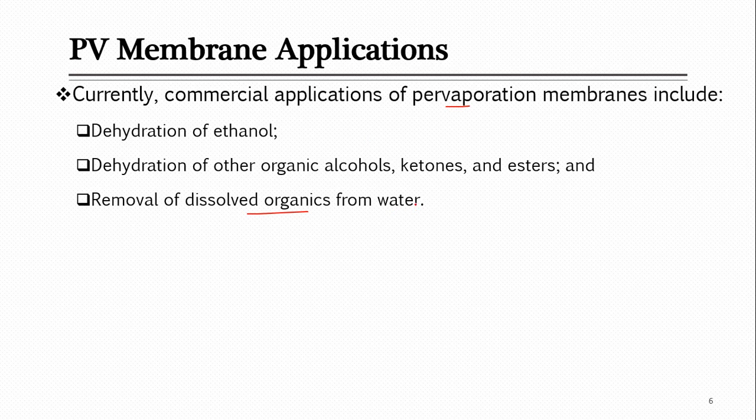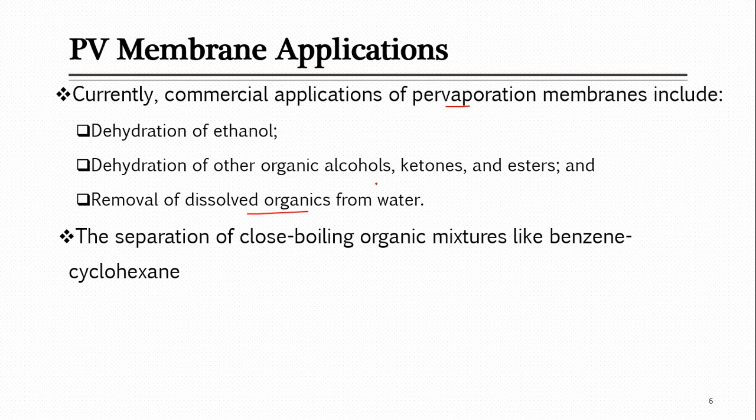If you remember, when we discussed liquid extraction, at the start of that lecture there was an application of liquid extraction for removal of water from acetic acid. In such a case, you can use either liquid extraction or a membrane, but as you have studied now, membranes are better than those techniques because they are compact, they cost less, the equipment is smaller in size, they are easy to install, and they have various other advantages. Membranes can be preferred compared to other techniques.